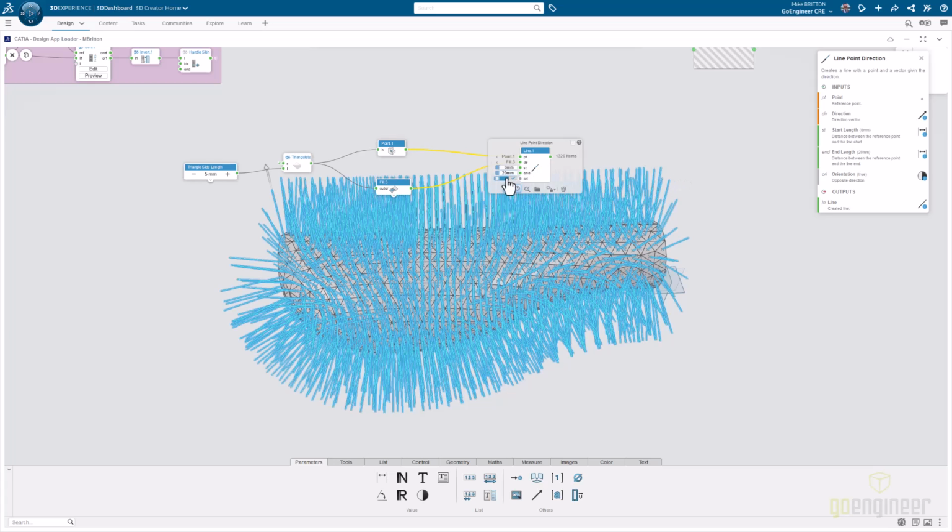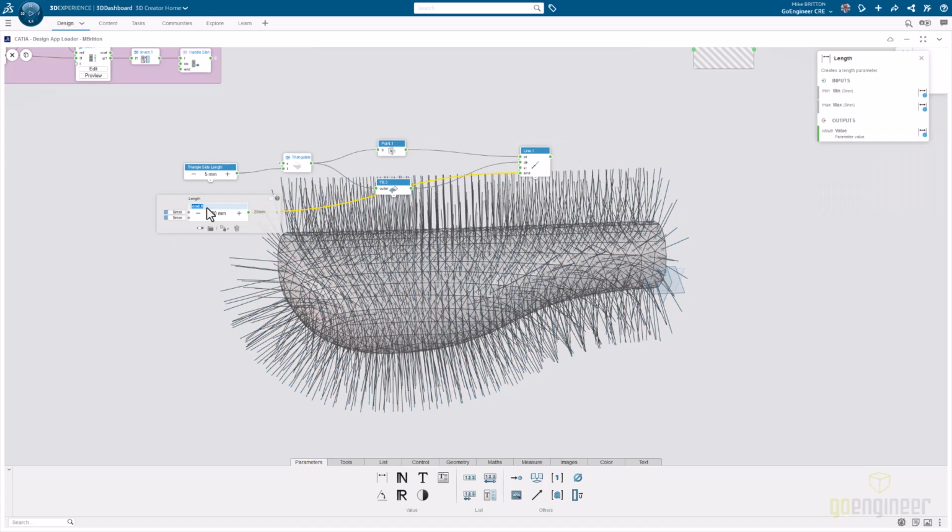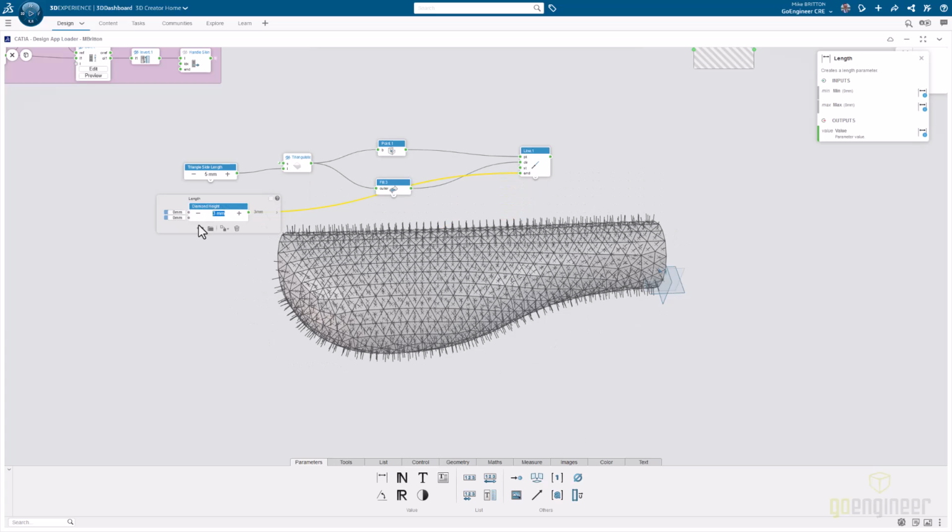The overall length of these lines, I'm actually going to make a controller also, bring it way over here. I'm going to call this the diamond height parameter, and I'm going to set this to 3 millimeters and make a controller out of this also. This is going to come into play shortly. So, okay, we have a bunch of lines. We have a bunch of triangular surfaces.